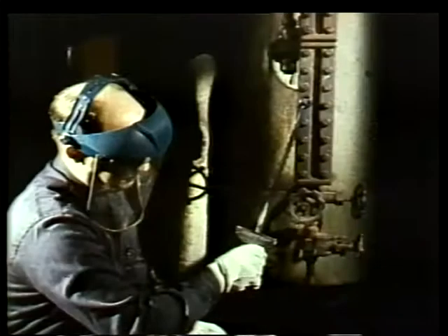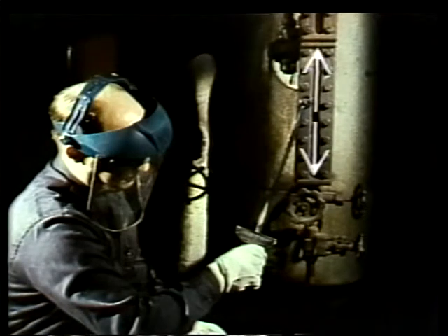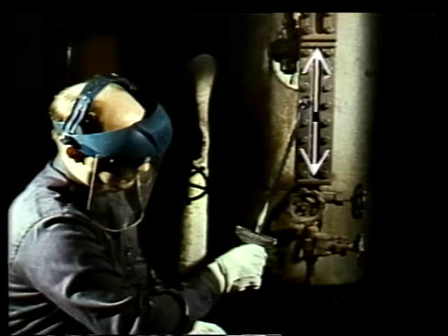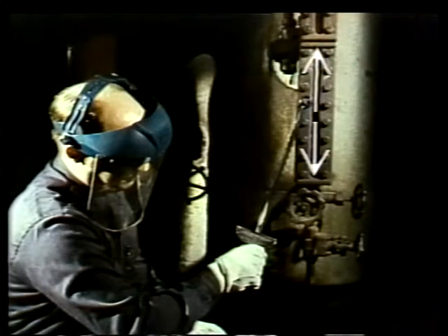Retighten the bolts with a torque wrench. Start at the center of the gauge and work outward, alternating between top and bottom and applying the manufacturer's recommended full torque to each bolt. Heat the gauge the same way as last time and see if the leakage has stopped. If the gauge still leaks, you'll have to completely disassemble it again. If there are no leaks, the gauge can be placed in service.